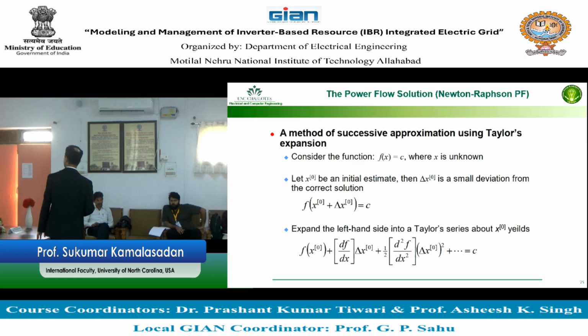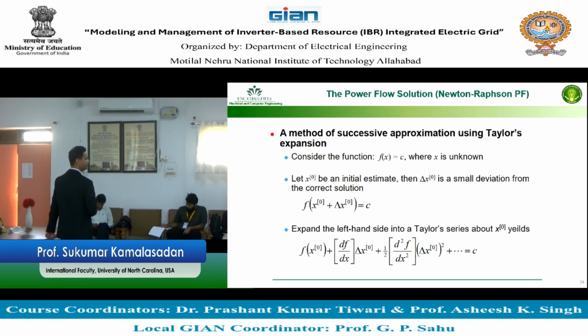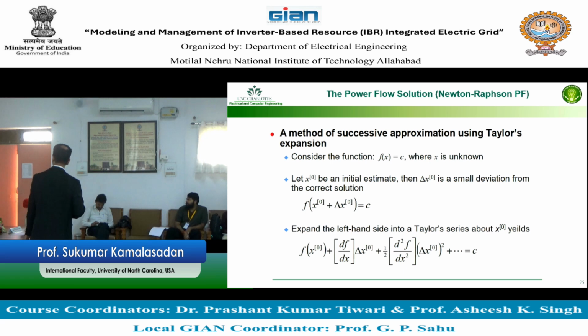And after you get the Y bus, you can write the nonlinear equation that is coming from expansion of the nonlinearity with the change in the deviation, and based on what we call a Taylor's expansion. I don't know whether Taylor expansion or Taylor series expansion you might have heard in your undergrad. What does a Taylor series expansion mean? It means that any higher order system can be represented in the form of change of that function with respect to the change in the variable. These are not a differential equation.